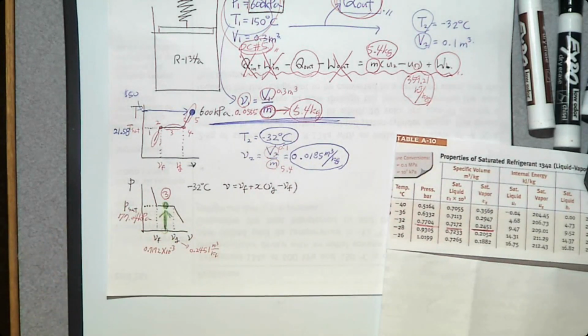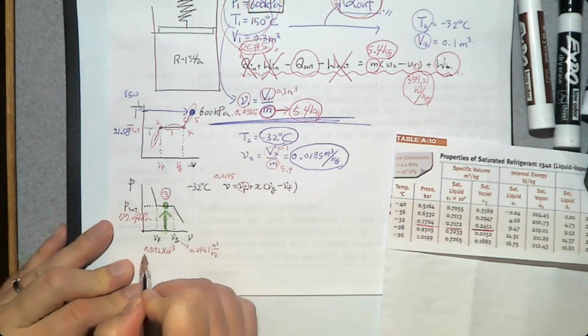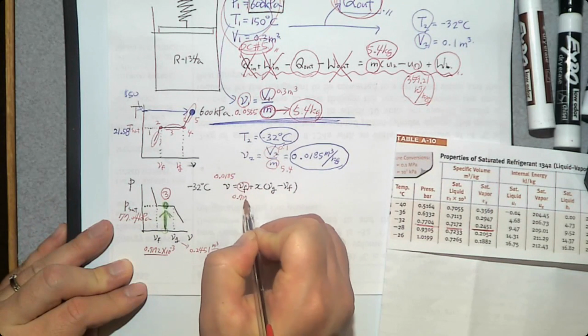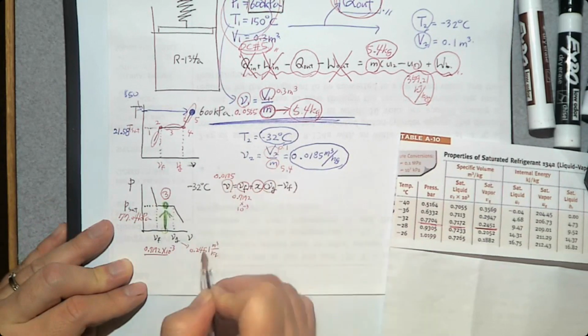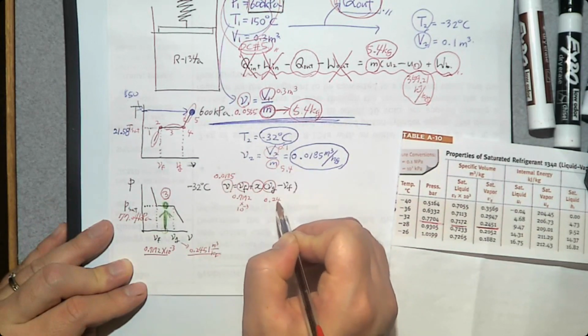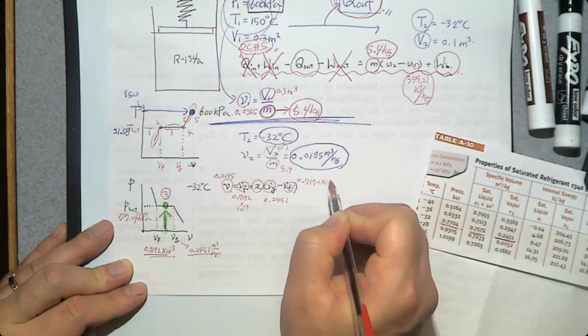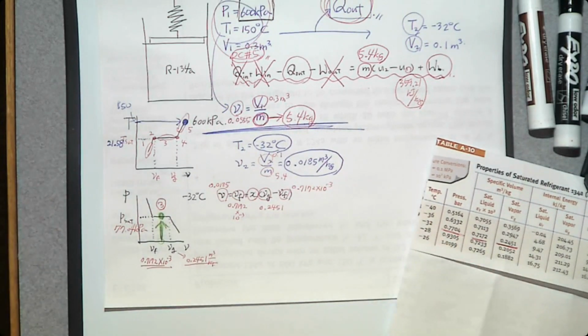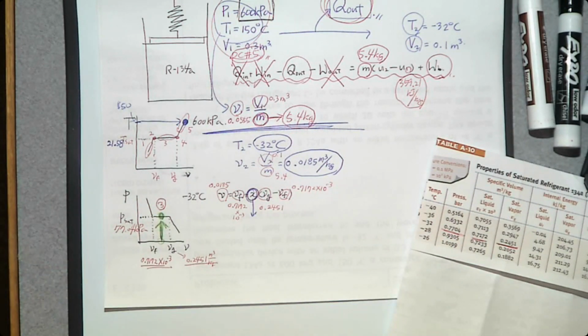In this equation, we already know v, 0.0185, and vf is right here, 0.7172 times 10 to minus 3. x is unknown, and vg is right here, 0.2451. vf is here again, 0.7172 times 10 to minus 3. So we have everything but x. Can you determine x? No. Yes. So if you do, x is...